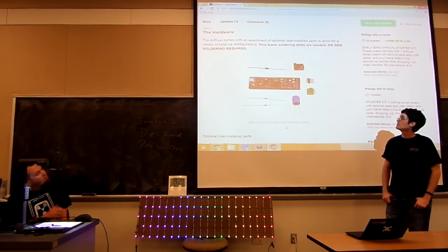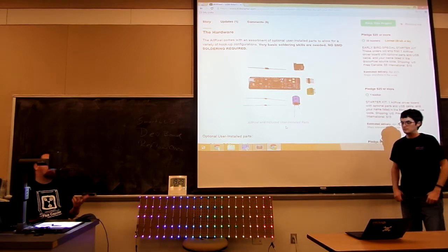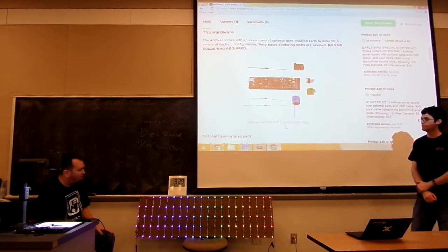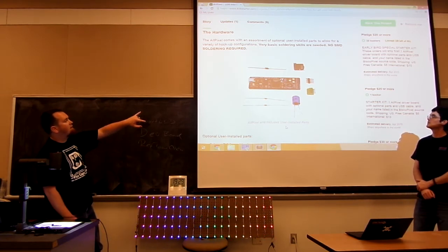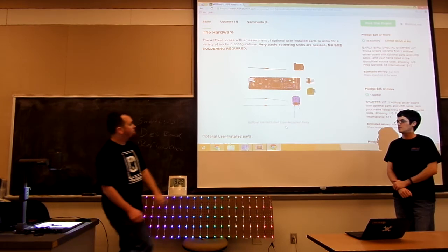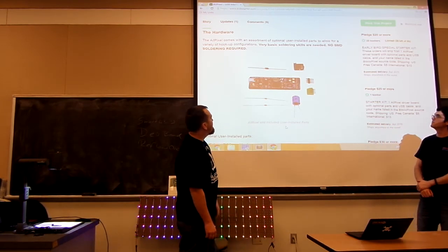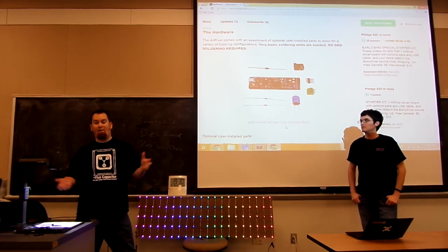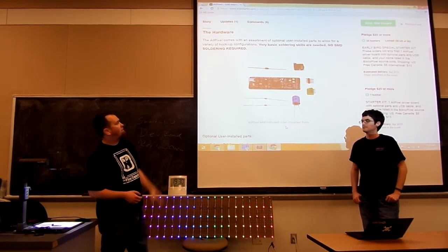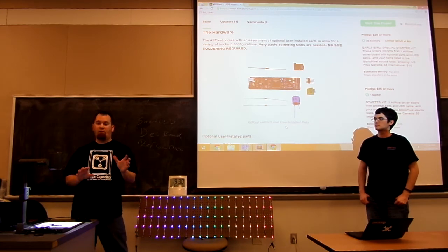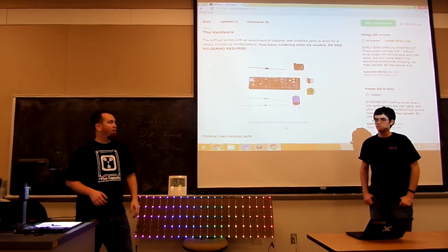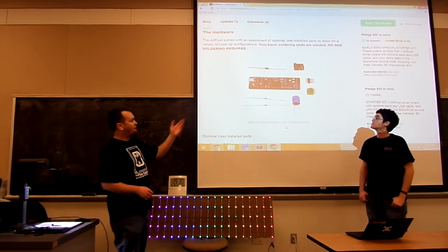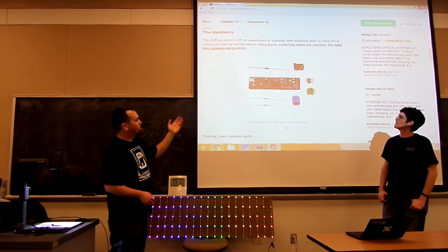We've provided a bunch of optional components, basically because we don't necessarily know how everyone's going to want to hook it up. There's a lot of options. There's the barrel jack for doing power like we've got here. The diode at the top there, you can place it in that spot on the left of the barrel jack, which allows you to power everything off of USB. Obviously, you're limited to about half an amp. We do have a half amp polyfuse on there just to be extra sure. And the diode's there so that you don't later plug 12 volts into the barrel jack and fry your nice expensive computer. Again, we've got the capacitor for smoothing.